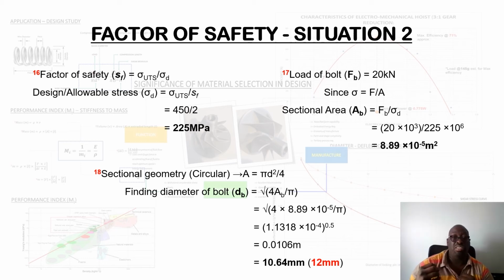Okay, so the greater the material allowance, particularly this cross-sectional profile, the greater the resilience of the material to operate within the yield limit, or below the yield limit of the material. The smaller the material variation, the more likely the material is going to deform above the yield limit. And in this instance, the bolt has been designed intentionally to experience some measure of plastic deformation before eventual failure. Okay. So again, it all comes down to what the designer's intent is.